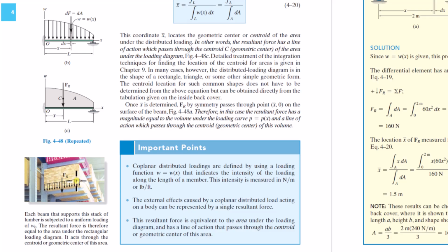I mean, it depends on the accuracy you're looking for and how in depth you want to go. Just remember, quality engineering is about the assumptions you make and when to use assumptions to make things faster, more efficient, cost less money. So you don't just go into absolutely as much detail as possible. That's not good engineering. If you can make a uniform distribution assumption and that works fine for the problem you're trying to solve, then do it. That's good engineering. But again, you're going to choose the load distribution to represent where the load is coming from.